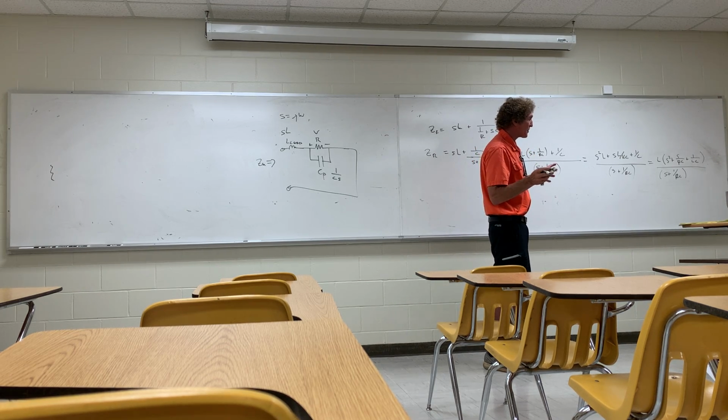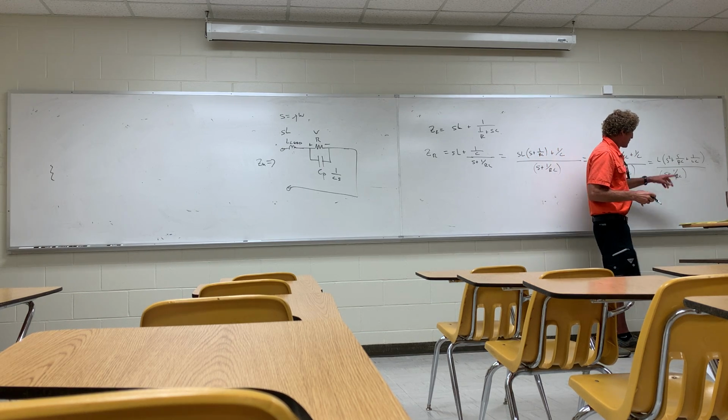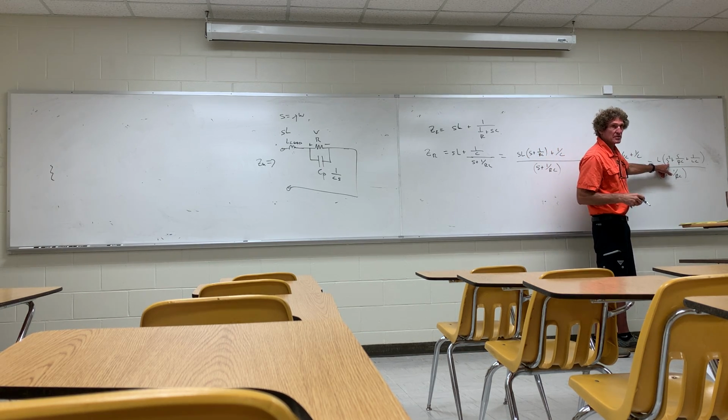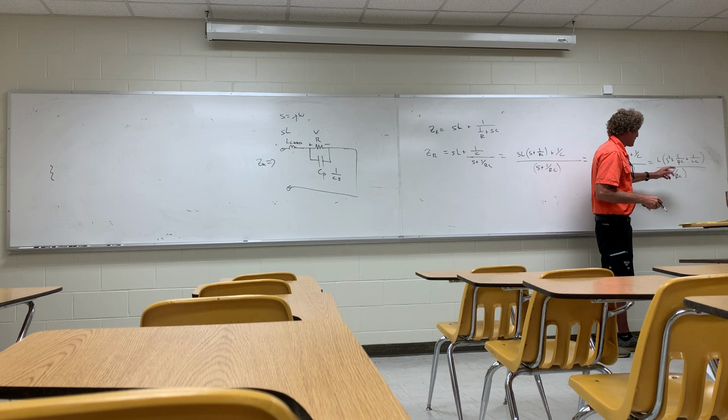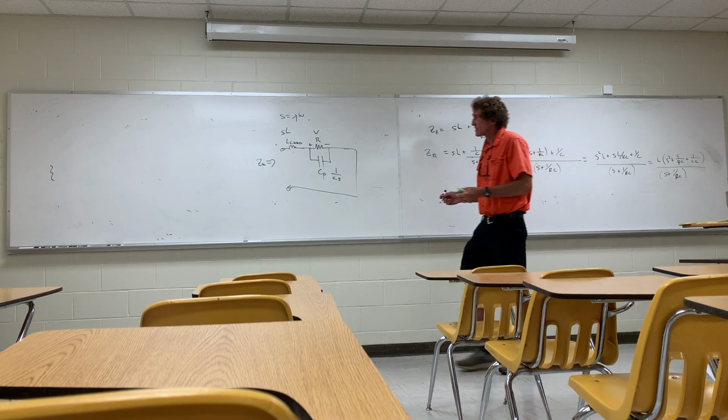When you do this at first, you've done this a few times, we can factor this depending on what R and C are and L, right? And you can either have complex poles or just both real poles or a double pole. Y'all follow me on that, class? You don't know yet. But one thing for sure is I'm going to have the 1 over RC here times S and 1 over RC down here. And here's what this looks like when you plot it.